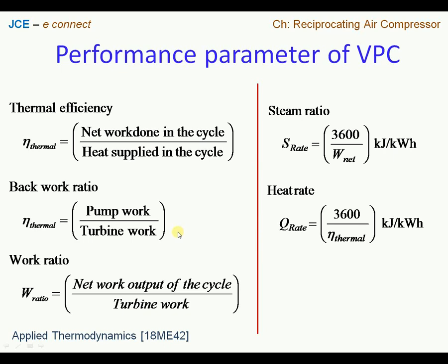Since the working of a steam power plant represents a kind of heat engine, when we looked at the Carnot cycle, we saw that practically it is not desirable, and we identified another alternate reversible cycle, that is the Rankine cycle, which fits very well for the steam power plant. Therefore the Rankine cycle is the ideal cycle representing a thermal power plant or steam power plant.